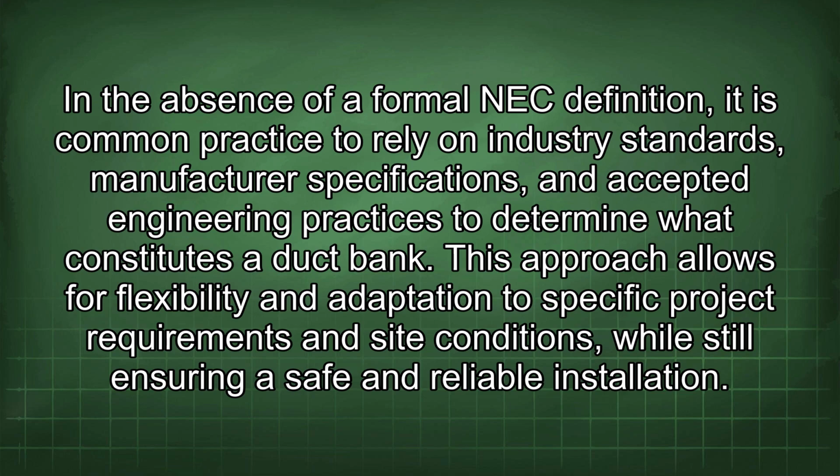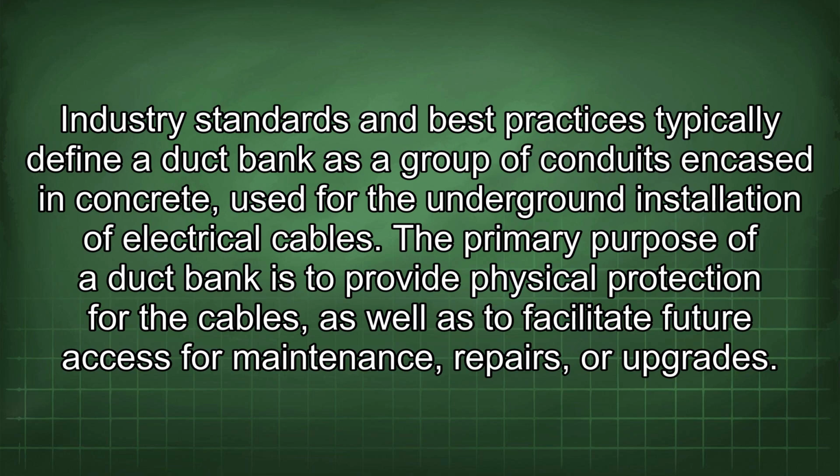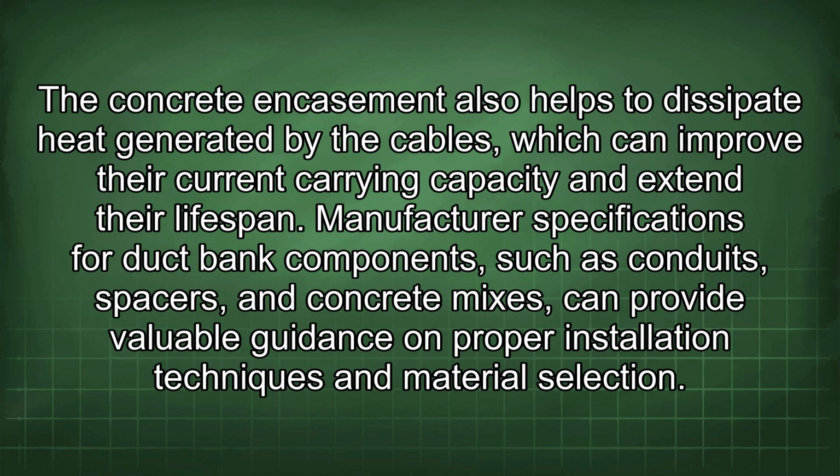Industry standards and best practices typically define a duct bank as a group of conduits encased in concrete, used for the underground installation of electrical cables. The primary purpose of a duct bank is to provide physical protection for the cables, as well as to facilitate future access for maintenance, repairs, or upgrades. The concrete encasement also helps to dissipate heat generated by the cables, which can improve their current carrying capacity and extend their lifespan.